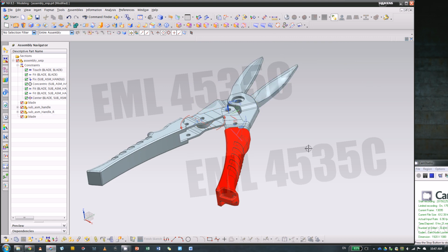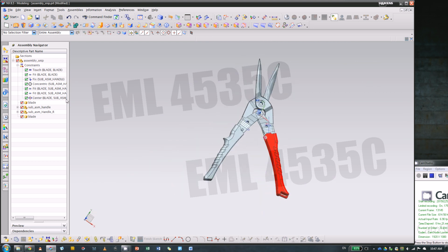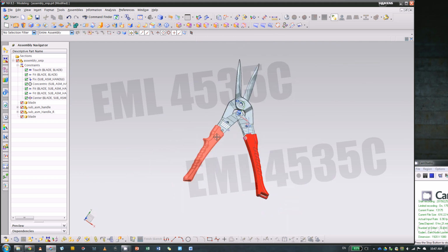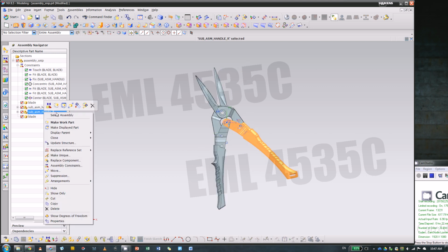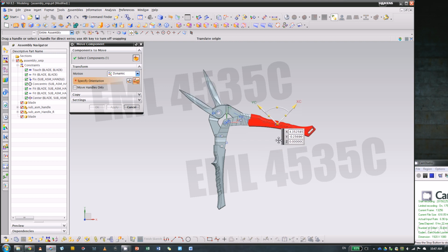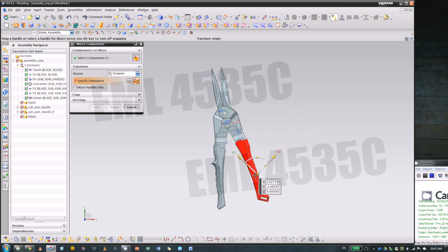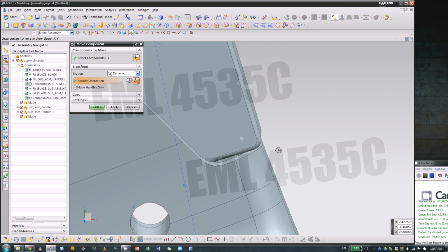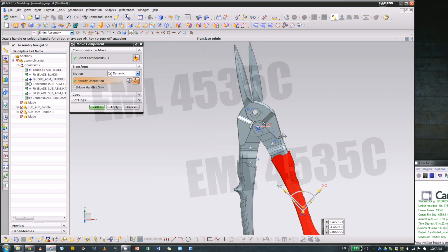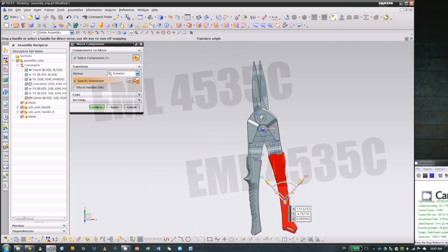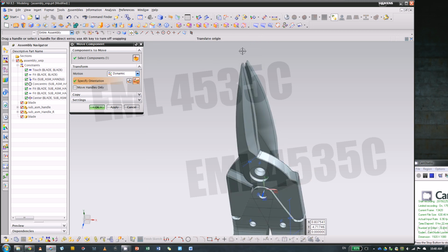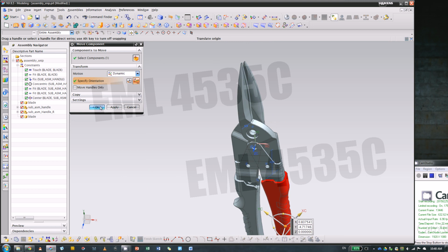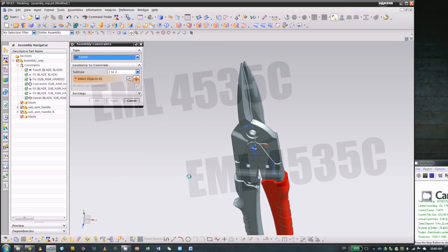So in this case, everything is done because we have a fixed for this handle. So this one will stay fixed, not moving, and we can try to move the red handle. And if you look closely here, in the real thing, this step actually prevents the snip from opening too much. So from the smallest closed place, you can use the constraint.